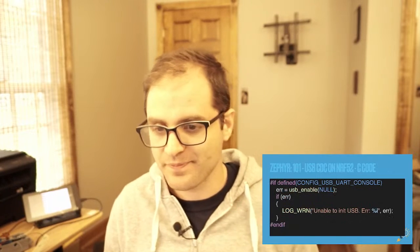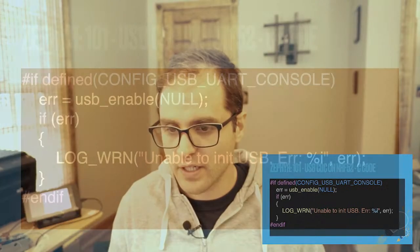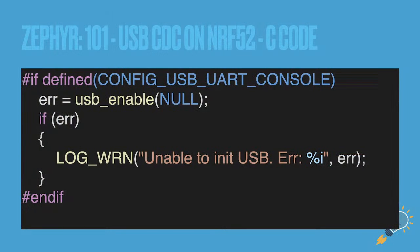Thanks, Zephyr. One thing that you have to do in your code, though, is you need to make sure that you enable USB. I've wrapped this in a macro, so if it's not enabled, then I don't want to do anything with it. But that's just one more gotcha in your C code if you have older versions of Zephyr.